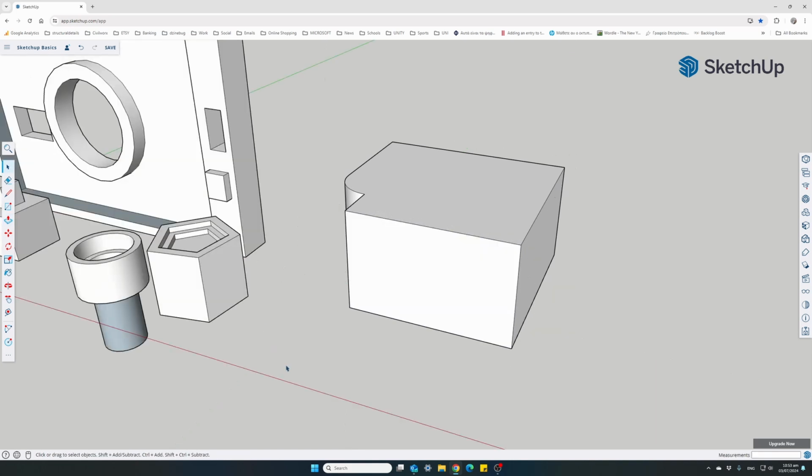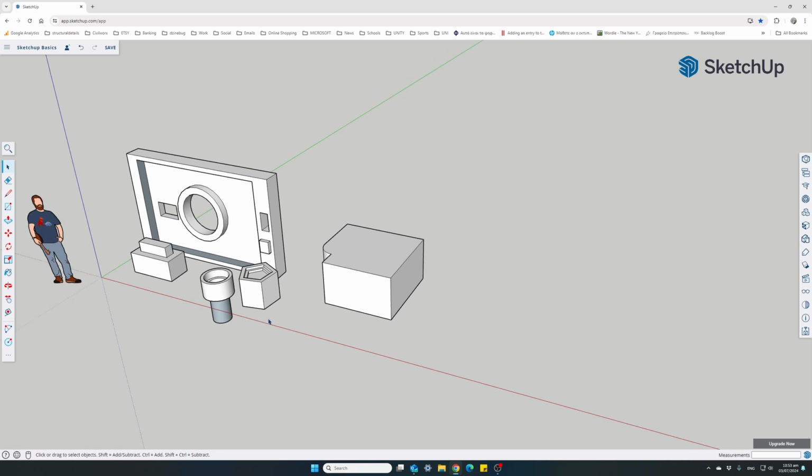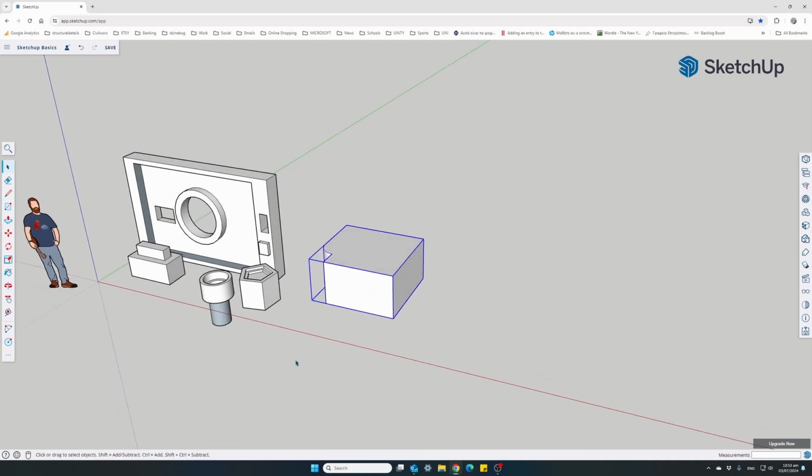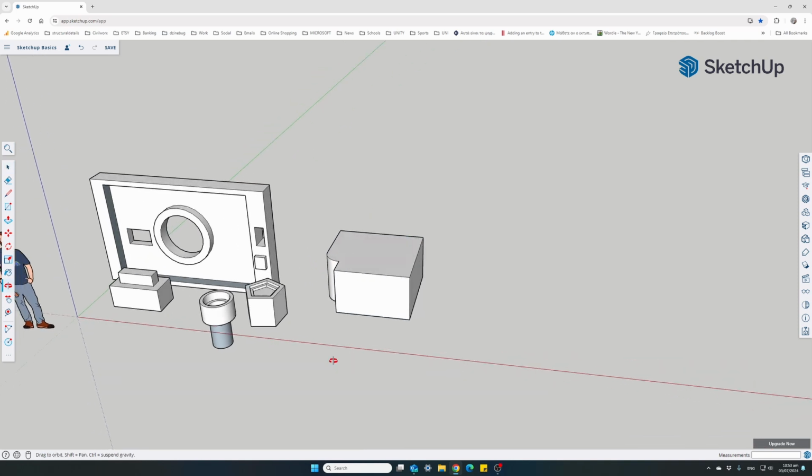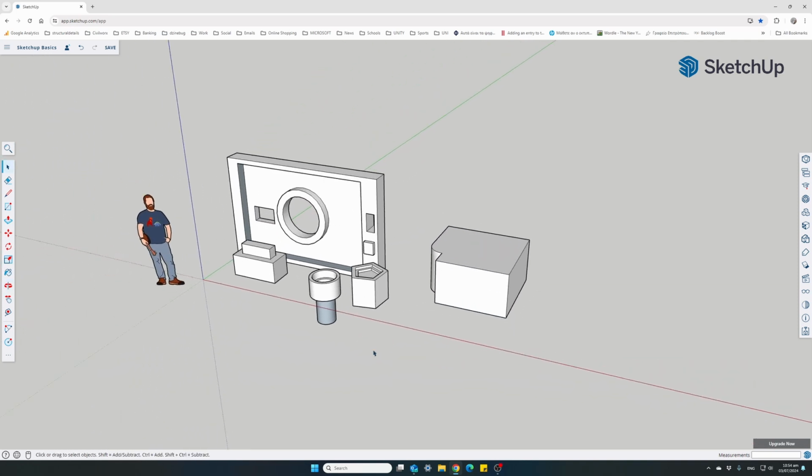Select tool, click anywhere outside, and we're back in our original state. This is still a block with the changes we have made. So I do really suggest changing your 3D components, converting them into blocks. It will save you a tremendous amount of time in your overall designs, and also I will show you another aspect of blocks when we are assigning materials onto our objects.